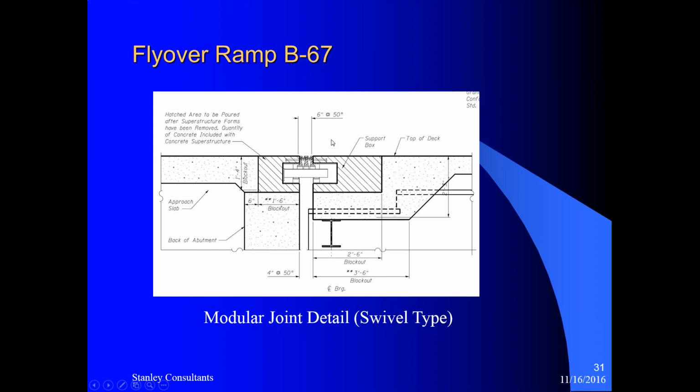And due to the length of the bridge, modular joints are also required, and due to the radial component of the movement, swivel type joints are usually used.